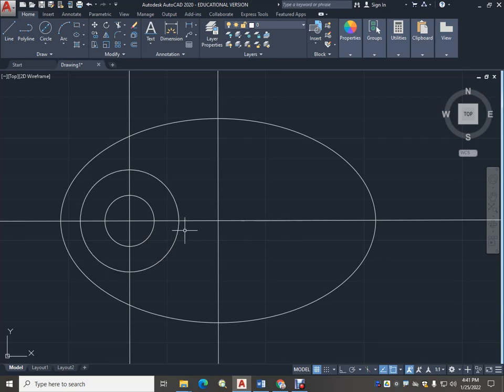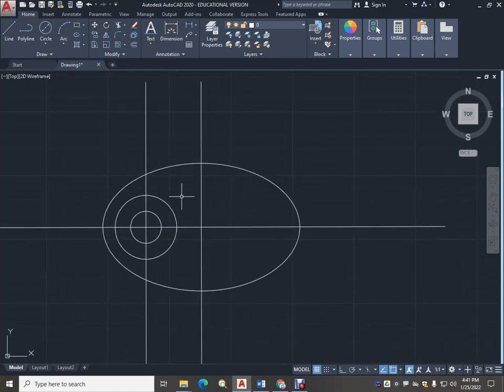Now, we don't need this as a solid cam, so we're going to open up a spot here on the inside to save weight and save material, and reduce the weight of it, in which shipping costs, less steel is a good idea, so we can open it up. So let's start opening it up by putting a ridge all the way around the line, and that ridge is set at 5/8.